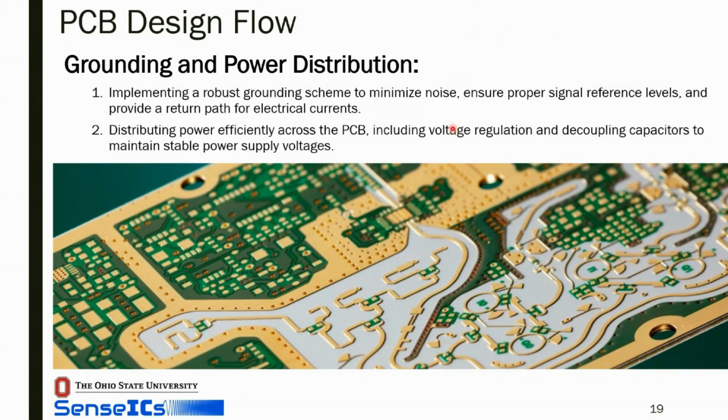Okay, so in this case, if this is an RF board and you didn't have this ground shield, maybe the noise from that RF circuit would couple into the other domain and completely break the board. So you have to think about that kind of stuff.